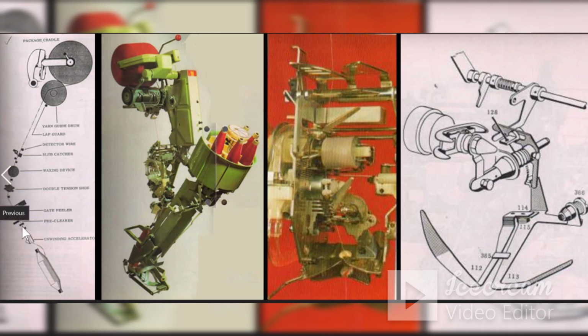By chance, if any yarn is trapped in the pre-clearer, that cutter will cut the yarn prior to ejection. Ejection means this bobbin is going to be thrown out of the spindle. So if its end is caught here, there will be difficulty in ejecting. So one more element that is not shown in the passage is a lower yarn scissor, which is located here.